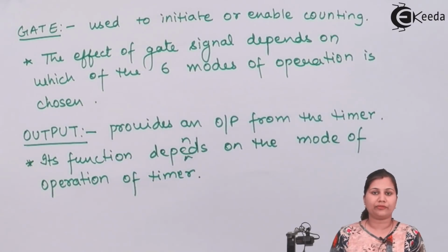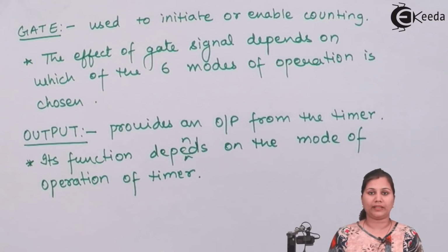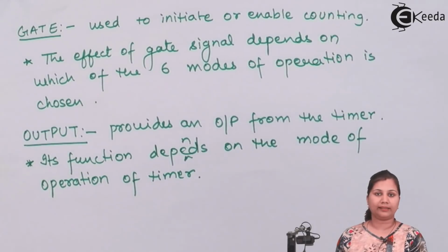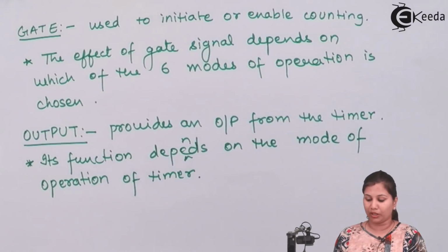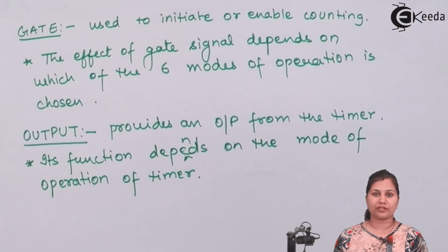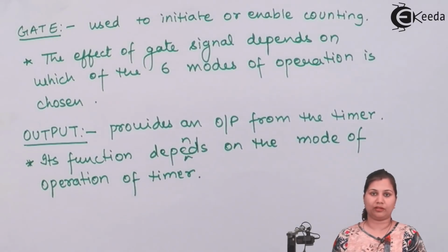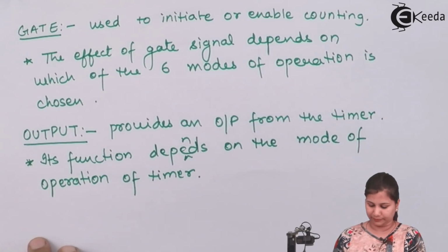So in 8253 we have 3 16-bit counters, which are down counters. That means they are initialized with a count, and then they decrement the count until its value becomes 0. Now, to understand how the timers work, let us see the internal structure of the timers.